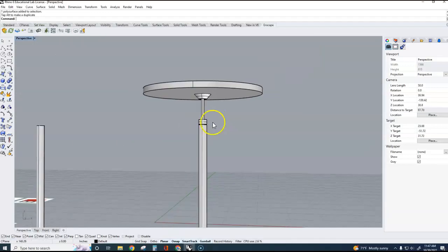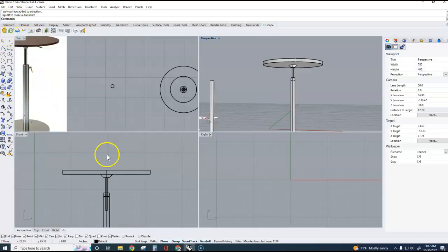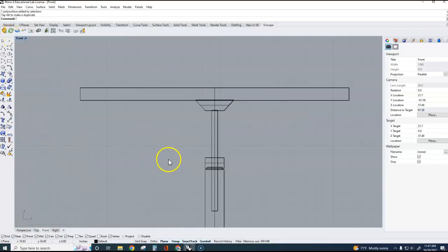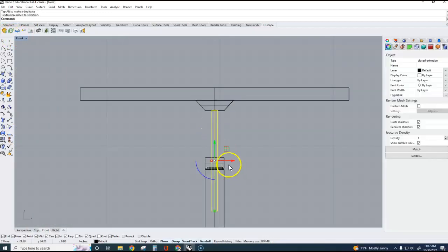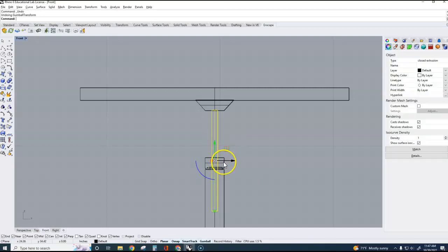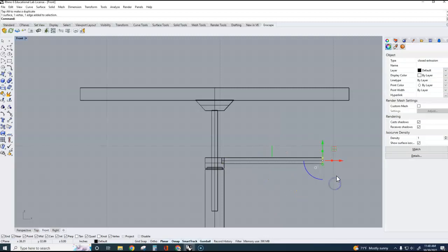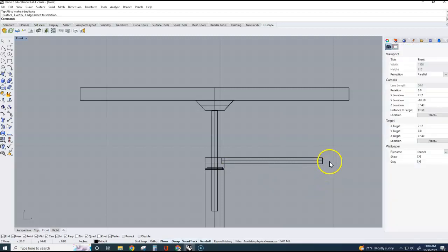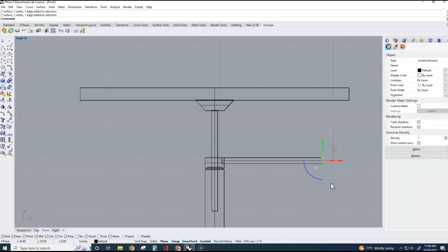And let's add those little thumb screws and thumbtacks. Again, rather than making it from scratch, I'm just going to take my shapes that I already have. Alt and then drag, and then hit this blue, click once, then I can key in a value. So here, instead of going to 3D view and trying to pick that face, I'm holding down Control Shift and I'm just windowing, which selects that face.